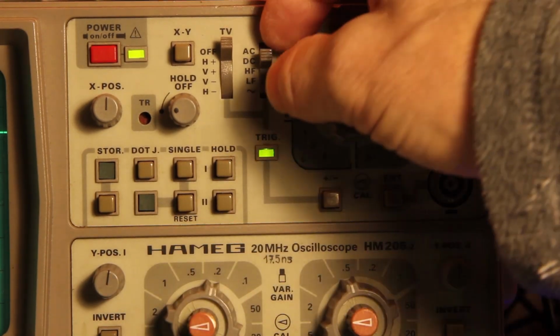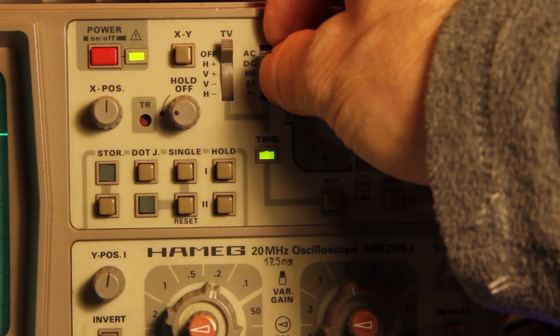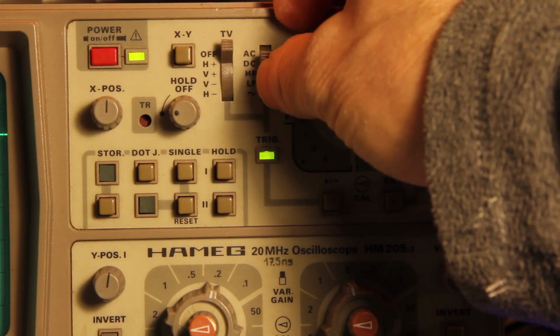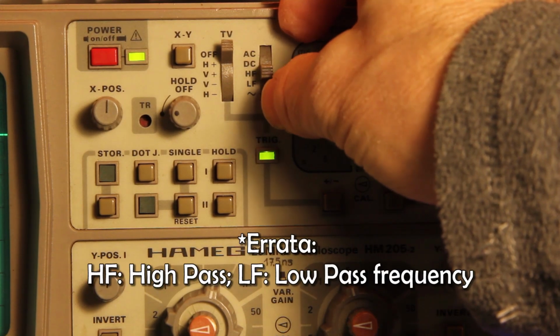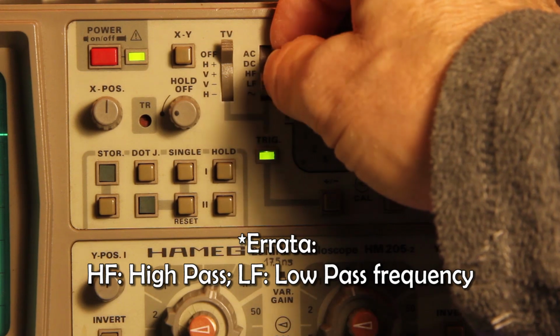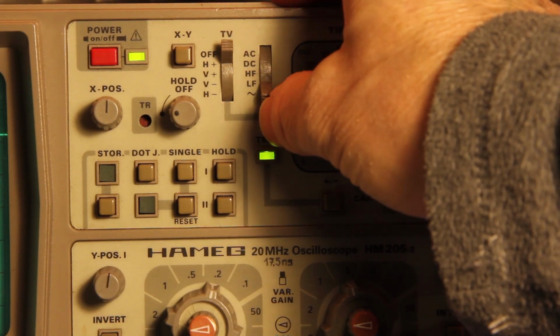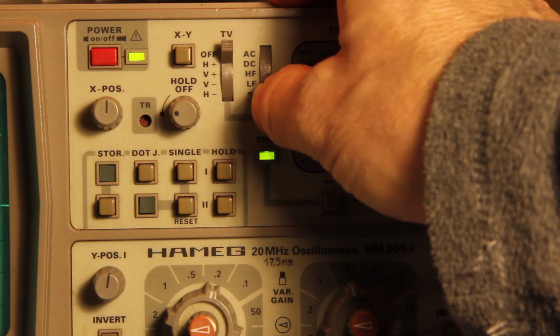And here a filter that allows us to pick the trigger level from the DC or the AC of the signal, exclude high frequencies, exclude low frequencies, and to synchronize to line or the mains voltage frequency.